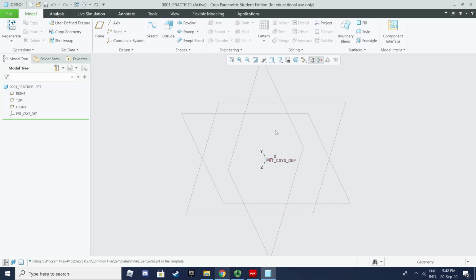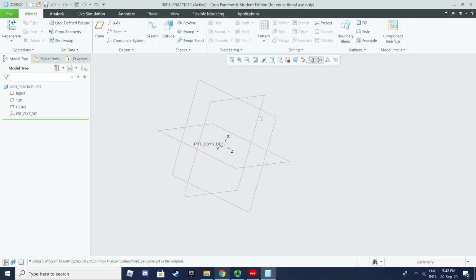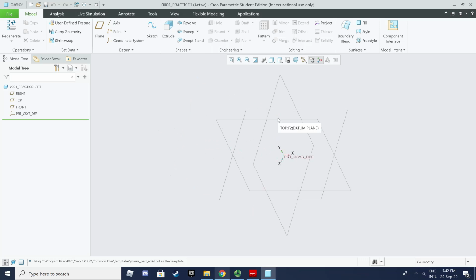then this thing is being shifted. You can see here, this thing is being shifted. And if you press the Control keyboard button while also holding the center button of your mouse, then this will zoom in and out smoothly. Let's say you rotate like this, and then you want to go back to the standard orientation. The shortcut is Control plus D, Ctrl plus D on the keyboard. Then you will go back to the normal orientation.